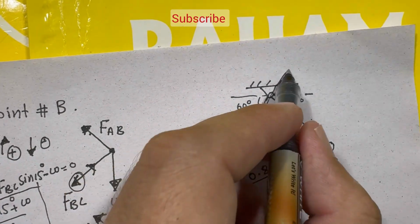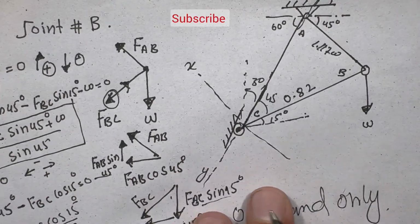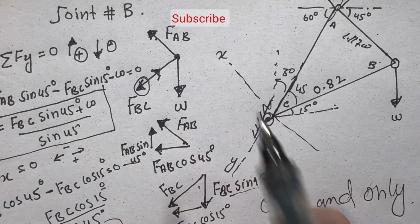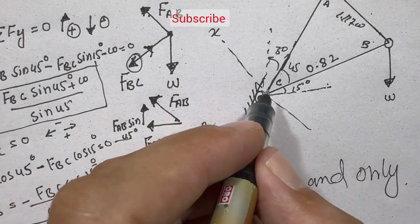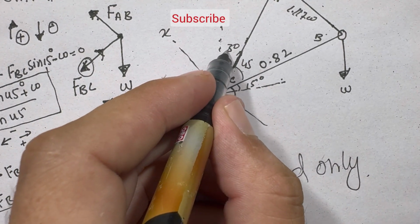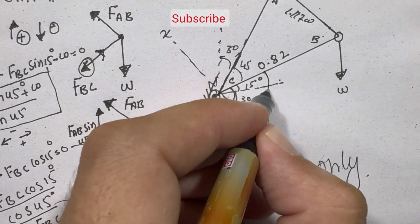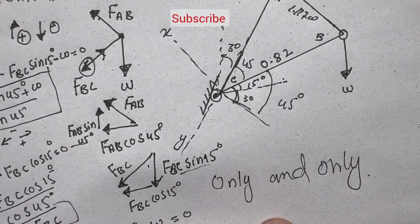For this joint, I align x and y with the coordinates. This member is aligned with the y coordinate. Now we find this value. If I push this 30 degrees, it comes out as 30 degrees here. This is 30 plus 15, so this whole angle will be equal to 45 degrees.